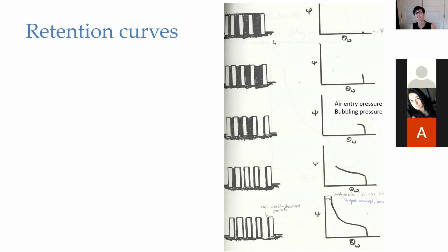If we start with everything fully saturated, we have this first picture here. The black is the water, and these things are the walls of the capillary tubes. Now we're going to start draining the water out the bottom. The first thing that happens is you start to get more of a pressure gradient; we're pulling the water down. This is under tension, so it bends down, and there's not so much water in it anymore.